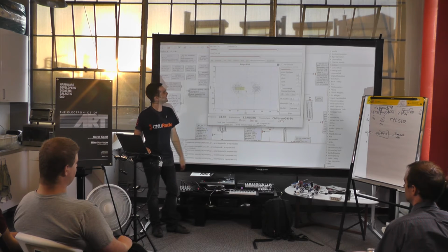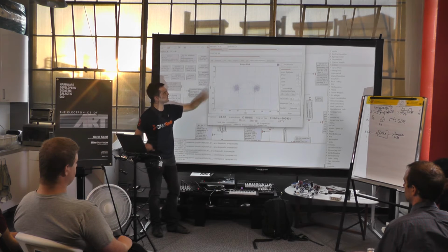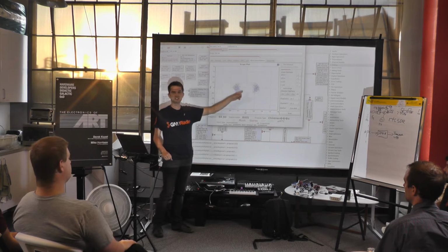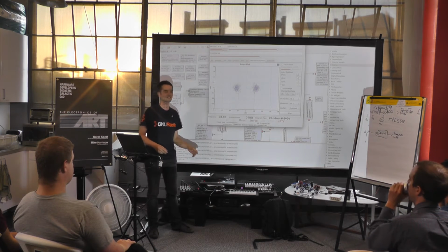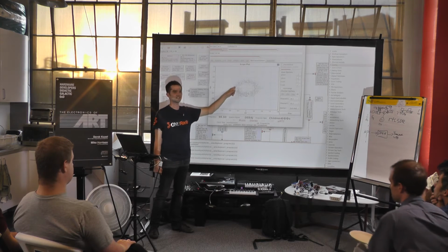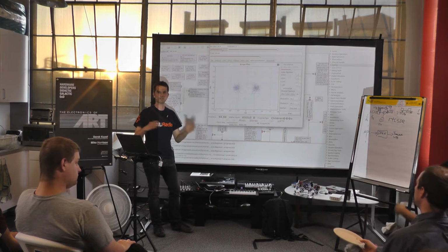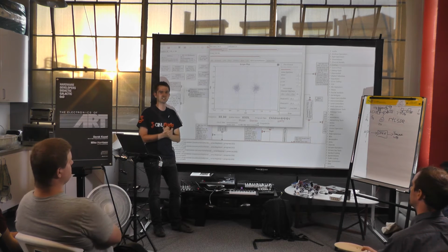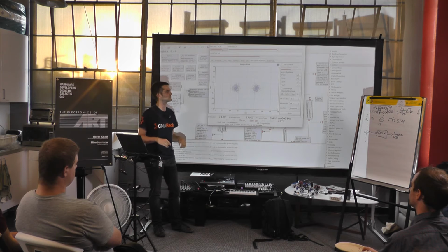Much better. Yeah, and so if I increase the gain a little bit, we should get this resolving a bit better. There we go. So this is the digital information. Digital ones and zeros. This is not a very complicated signal at all, and so it's transmitting ones or zeros. And there's a bit of encoding on top of that, so if you start diving into communications theory, you realize there's a lot of benefit to putting in some redundancy and putting in some channel coding so that if you get some noise, you don't get garbage out here.